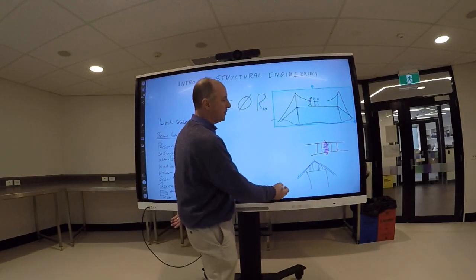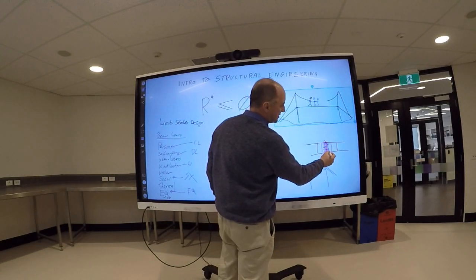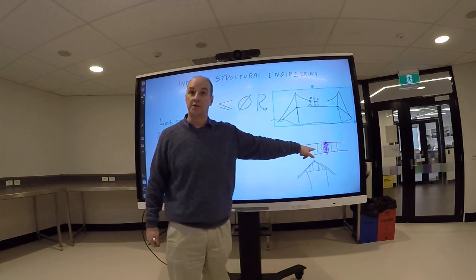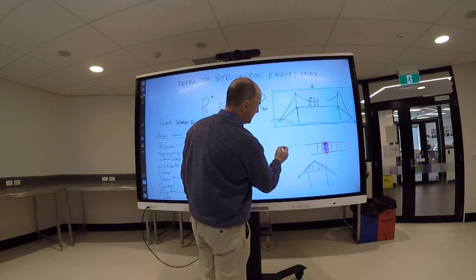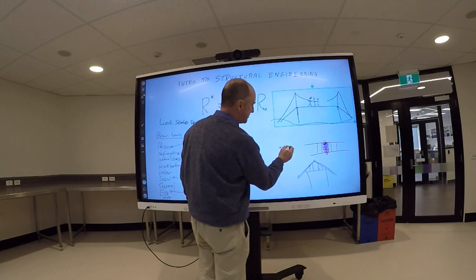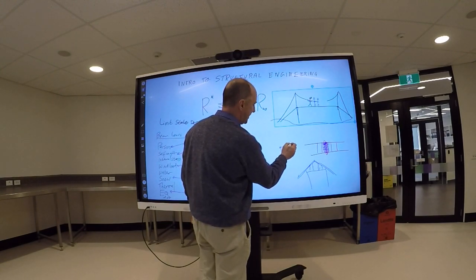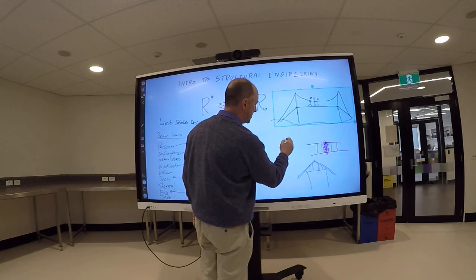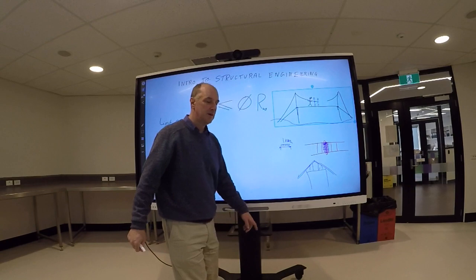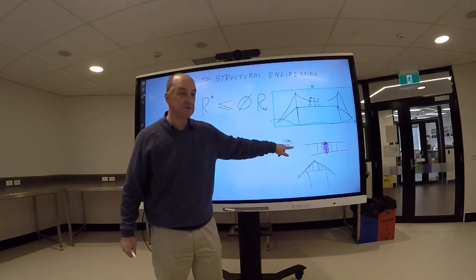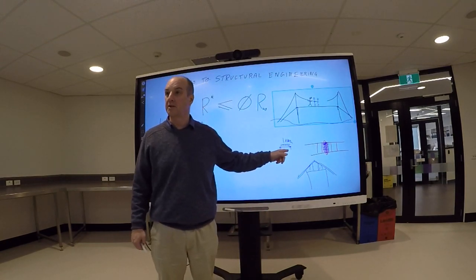But on this particular plank, let's say that's a meter wide, it has a zone of about 1 meter, it's got about a kilonewton on it. So we isolate that beam and we draw it like that. It's held up at the ends, and it's got a load pushing down on it, which happens to be 1 kilonewton per meter. So we've just taken that beam out, and we're working out how strong that beam needs to be.